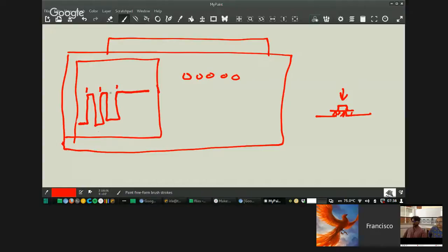Maybe it's going to be 7. You never know how many bounces the button will make. So you need to remove the bouncing. Or imagine you are sending some data through the serial port when your button is high. You are going to send it 3 times. So you need to debounce the button.